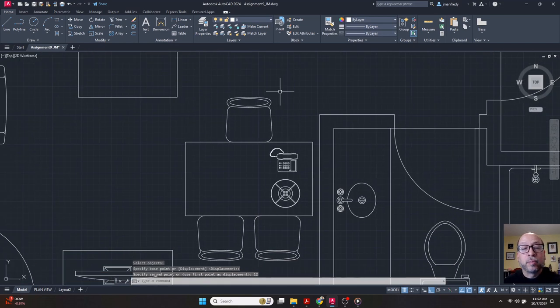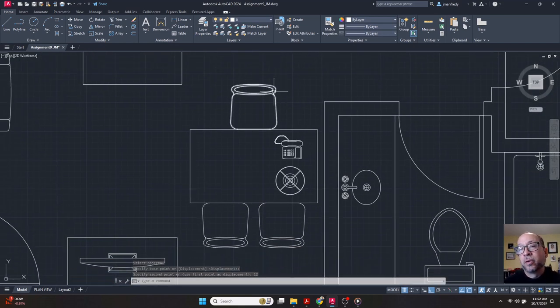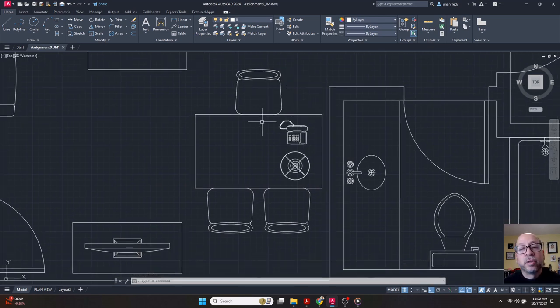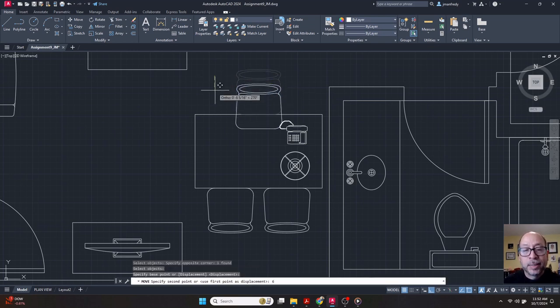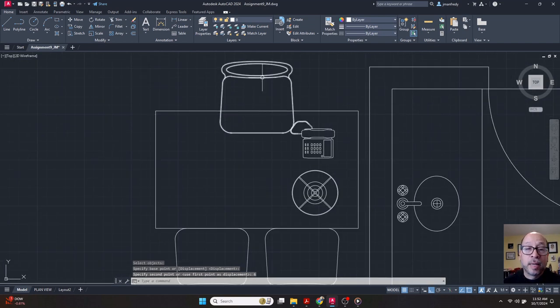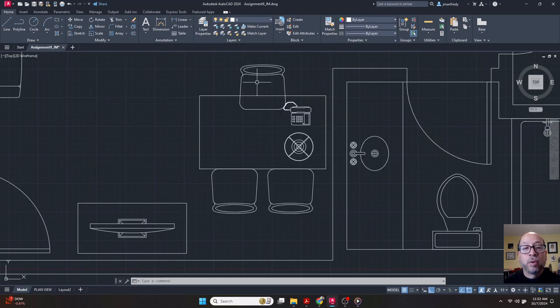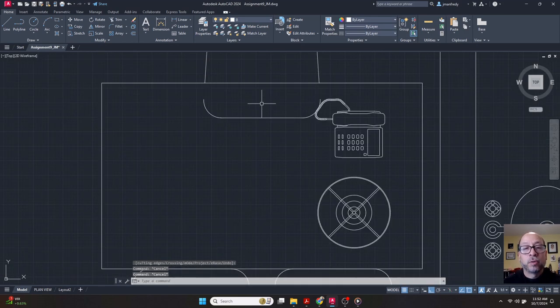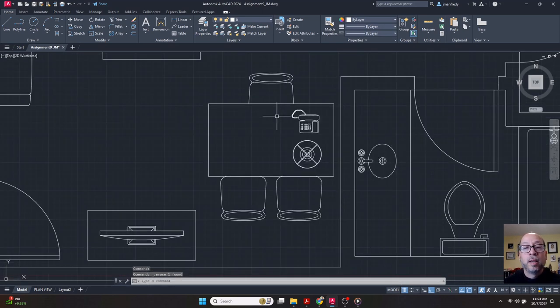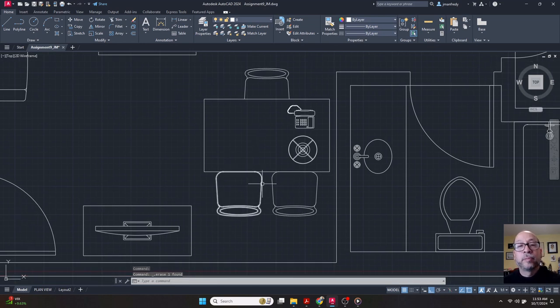If you want to create a drawing that's more akin to what they're including in their project file, half this chair is underneath the desk, basically. So I can move this chair downward, let's say 6 inches, and then explode the block and trim off the lines I don't need. So here I will X for explode that object, TR for trim, and I will trim off this. Then I'll zoom in closer and I erase these lines here that belong to that chair, used to belong to that chair. And then I'll have to do the same thing for these here.